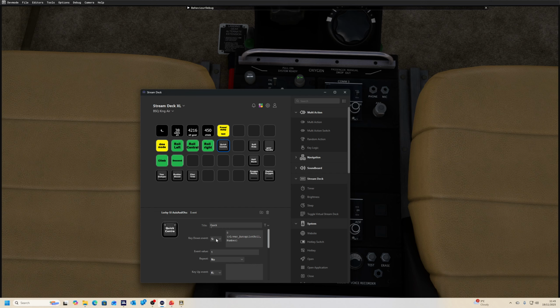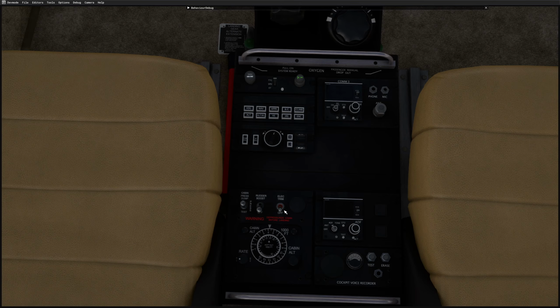Just literally, this is a little mini script, and it writes a 0 into the autopilot roll, and it does change nicely. It doesn't change dramatically. So let's show you that in operation. Let's have a serious roll to the right. So we'll bring that all the way over to the right, and if I press my quick center button, it just puts it back in the middle. So that's what I've done. I just wrote the script straight onto the button.